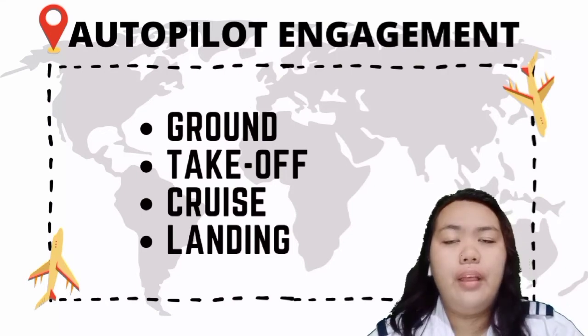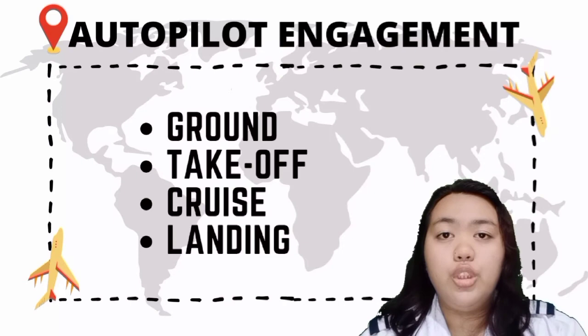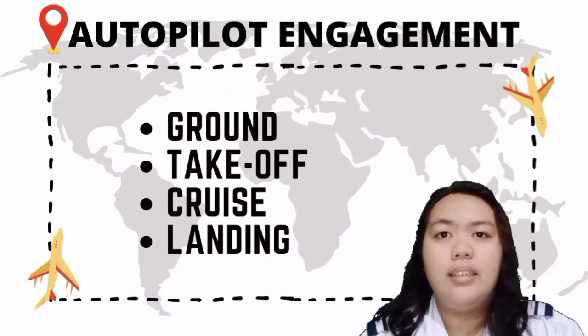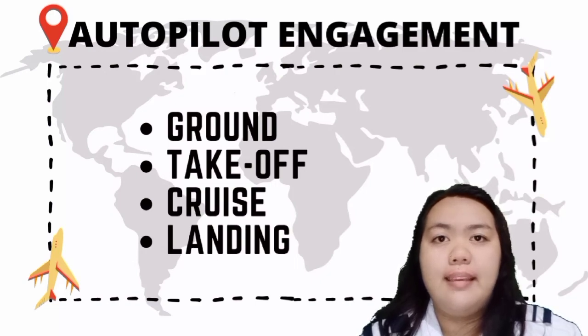During takeoff, the autopilot can be engaged provided that the aircraft has been airborne for at least 5 seconds or if the aircraft is above 100 feet or so. During cruising, only one autopilot can be engaged at a time. If the second autopilot is engaged, it will disengage the first one. During landing, as I have said earlier, both autopilots may be engaged to ensure the best level of redundancy.